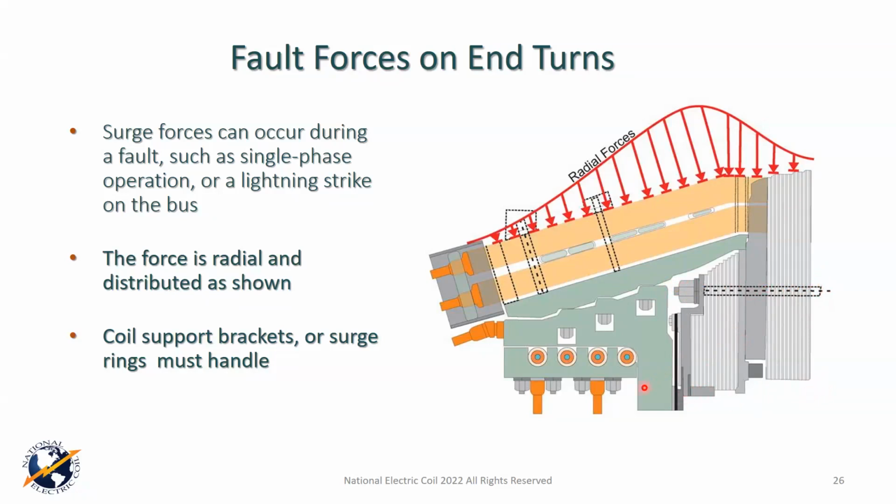But what's interesting about this, here's our coil support bracket, and they're supporting the phase rings here. And here's a cone. If you notice, that cone and the coils will be tied tight together. It'll allow this thing to move a little bit on these lands, at each one of these places. So it gives you some axial movement. But there's another mechanism in here to also allow for movement, and that's with the coil bracket itself.